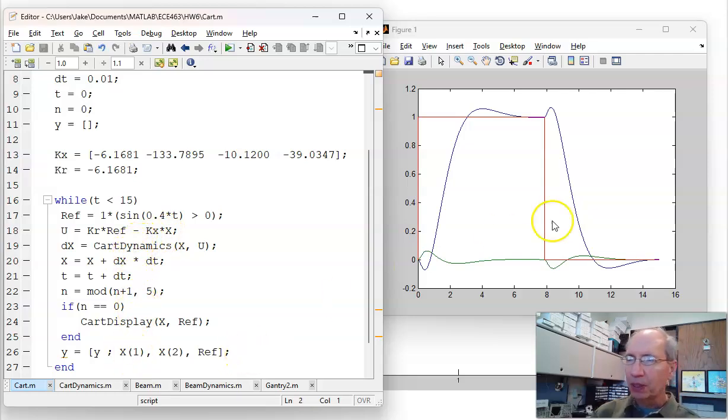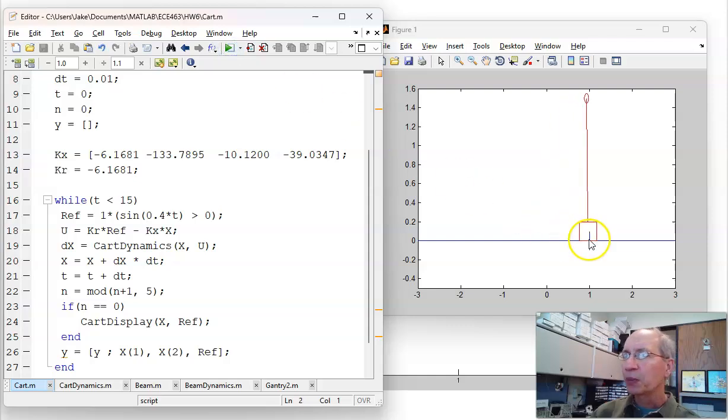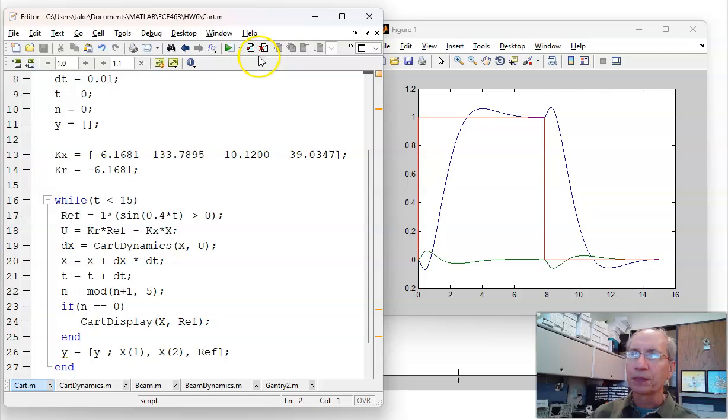Plot the outputs, and you get that response. This undershoot I don't like, but you're kind of stuck with it. Physically, the way the system behaves, to get it to go right, I first have to go left to get it to move, to lean. To get it to go left, I first have to go right to get it to start leaning left, then catch itself.